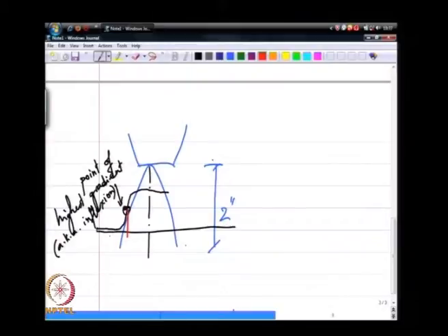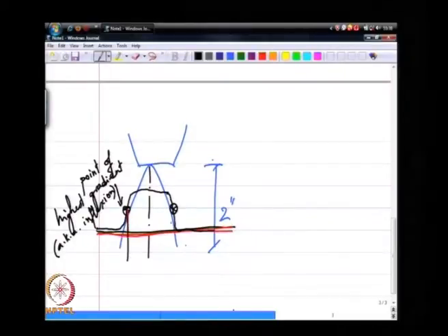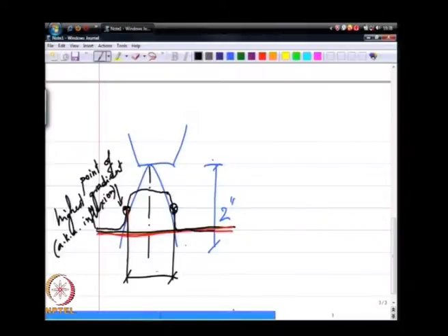So, essentially I look at the whiteness of these pixels of this line array of pixels. So, whiteness as in a grayscale, and it goes from nearly pitch black on the outside of the spray to where the liquid drops reflecting light back towards the camera look whitish at a higher grayscale number, and when I plot that quantitatively I get a plot that looks like this, and from these two inflection points I can get the width of the spray.